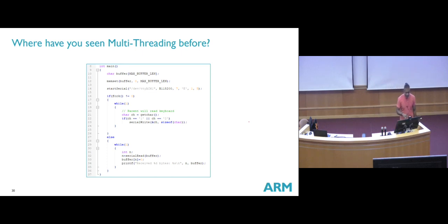This is actually from your RPi code. If you remember, it communicates with your Arduino Uno, correct? On the Uno, we have interrupts for transmit and receive on the serial interface. But on the RPi, we don't have interrupts. So how did the transmit and receive happen concurrently?